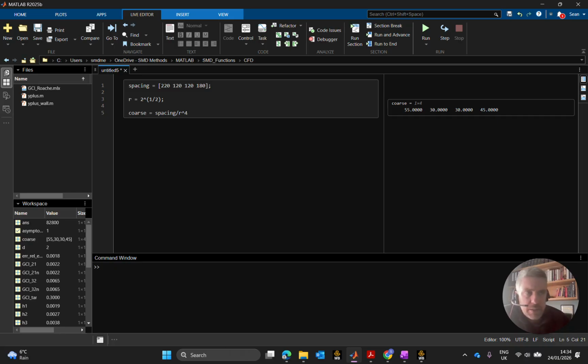I think it was the ANSYS Fluent Theory Guide that said between 75 and 100 spacings along the wall. So like that 120 probably would be what I need for this turbulence model, and it will also say that's the spacings you need to get good results. So I don't expect to get good results in this mesh. So I'll lessen the pain on that slightly.